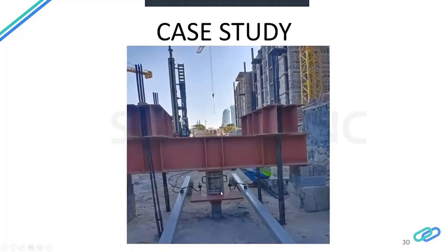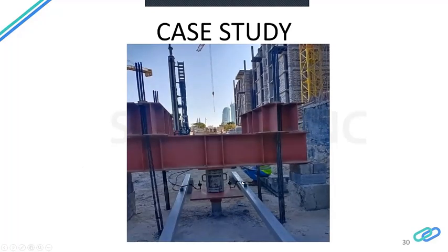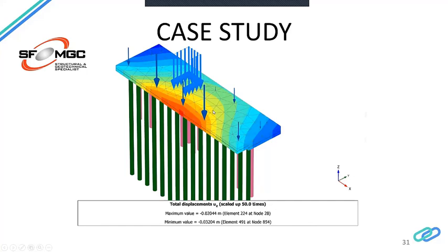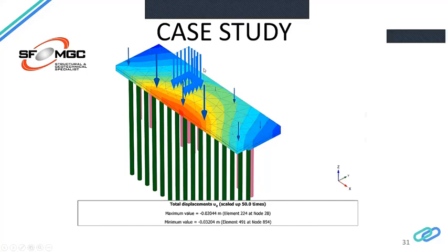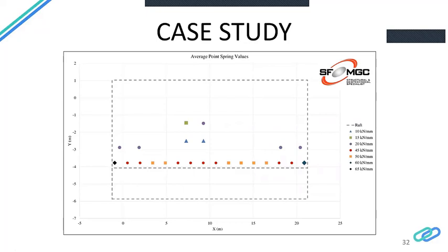This is the micropile load test we have conducted on the site, and we have used it to calibrate the finite element model. And this is the worst case scenario in the worst phase results. The deformation is barely 32 millimeters, and the safety analysis was conducted, and the safety factor was in excess of 3 almost for the whole system.